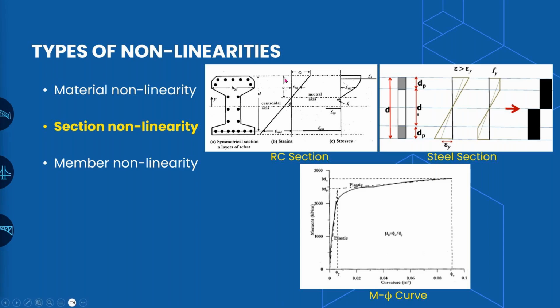So what we do is increase the strain at the concrete level up to its limit, and compute the corresponding stress, and on that basis we plot a graph called a moment curvature curve. The moment generated in that particular section at one particular curvature is plotted in a moment curvature format. If you do this exercise for n number of points, we get a curve something like this. It is very well visible that this curve is nonlinear in nature.